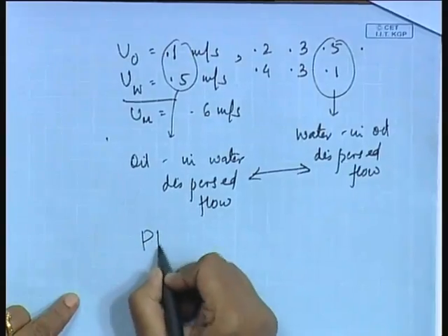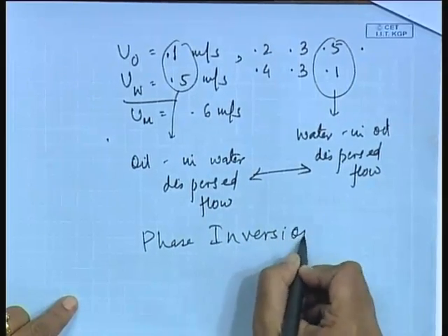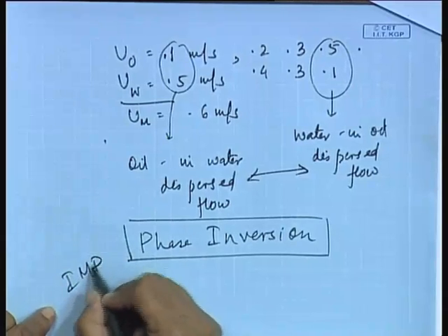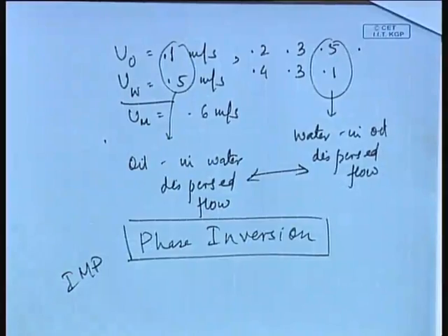For liquid cases, this particular word is very, very important. You are supposed to remember this: the phenomenon of phase inversion, during which one particular dispersion inverts to form another type of dispersion. This is usually characterized by a sudden change in the pressure drop.